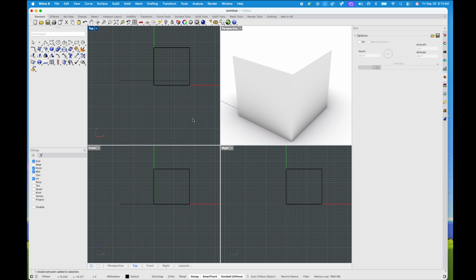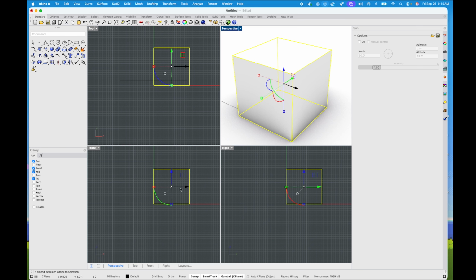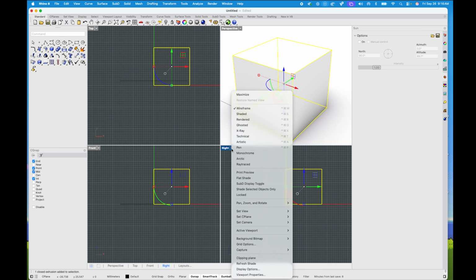You'll notice that it instantly gives us the top view, the front view, and the right view. Again, kind of already what's being asked for. In our case, if you wanted to switch those, like maybe, oh man, I'd really want the front on this side, I want the left side on that side. Great. Well, if you click on that little down arrow, you'll see a ton of options. In our case, we'll set the view, and we could set it to anything.